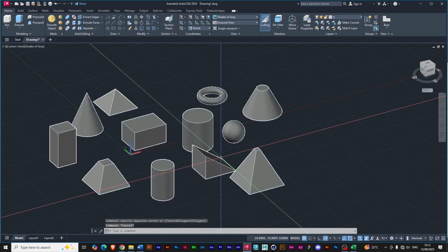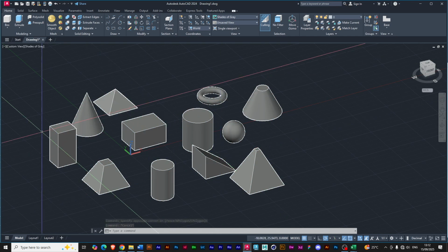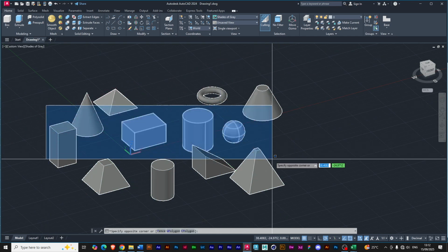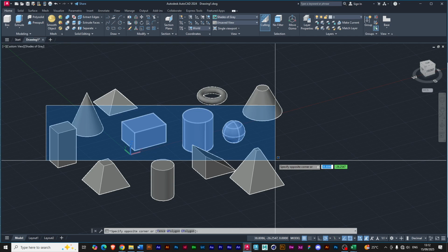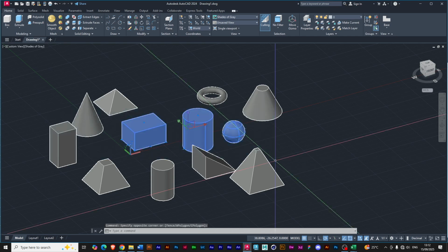The blue marquee goes towards the right and picks only what it engulfs. Anything not engulfed, even though it touches it, will not be selected. What is engulfed? Only these three things here. This one isn't engulfed. That isn't. None of the other ones are. So only three things will be selected. That's the blue marquee.